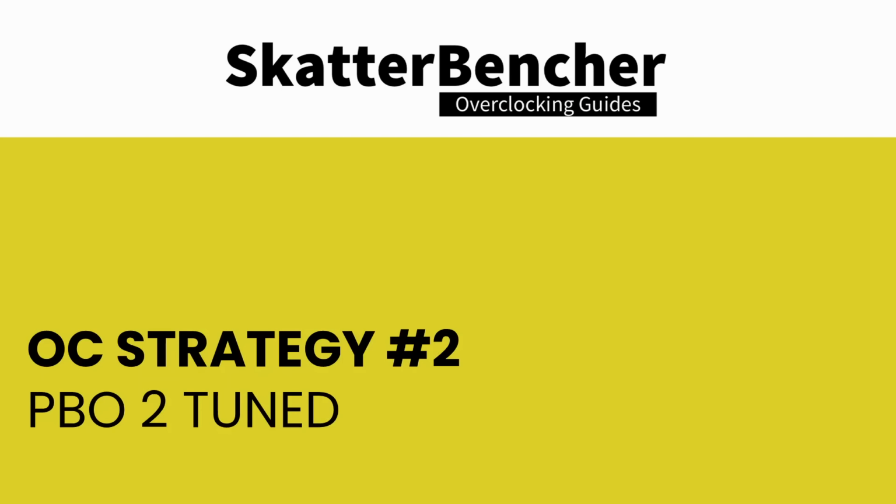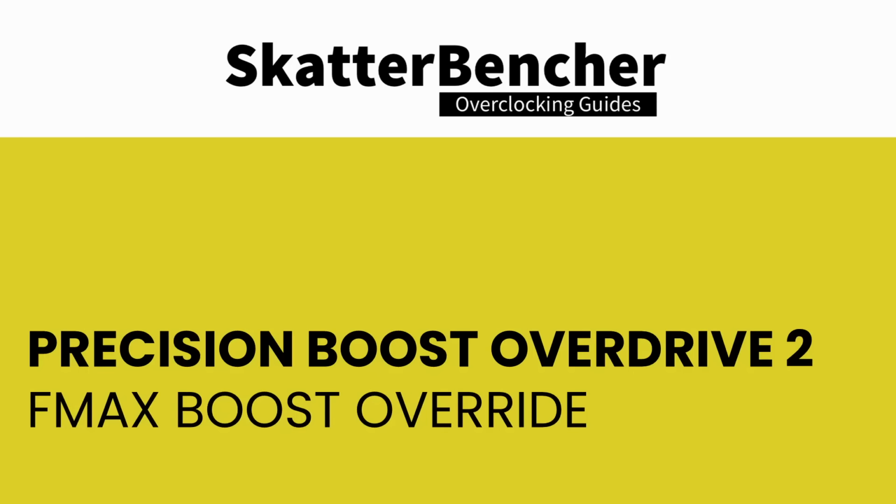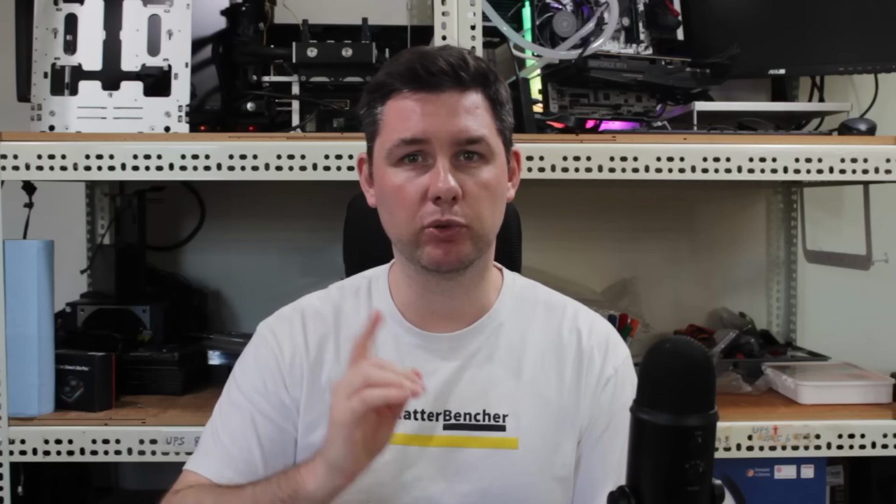In our second overclocking strategy, we tuned the CPU's Precision Boost boosting algorithm using some of the tools that are available in the Precision Boost Overdrive 2 toolkit. Fused maximum frequency, or Fmax, is one of the Precision Boost infrastructure limiters constraining the CPU performance. Basically, it defines the maximum allowed operating frequency of your processor.